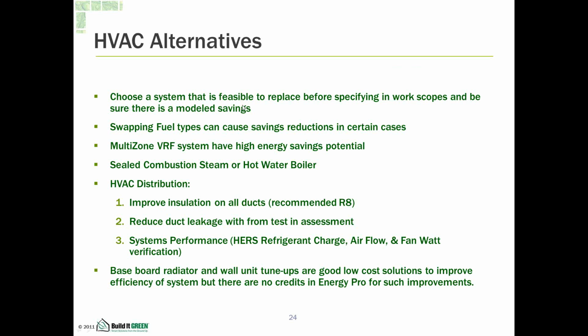So again, you always want to make sure things are feasible before putting them in the scope of work. Especially with HVAC systems, you definitely want to make sure you can have clearance for any flues, any kind of exhaust issues. If you're changing out fuel types, make sure their savings can be shown, or if there are reductions. There can be reductions in some cases, so be advised on that.